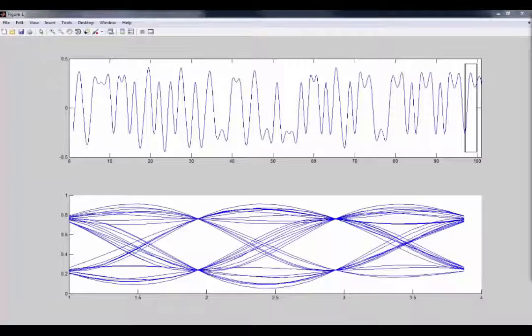And you should be able to see right away that there are certain points in time where all the waveforms clearly can make a 1 or can make a 0. And this says that if we were to come in and sample right at this time, we'd get exactly our 1s and 0s as we planned.